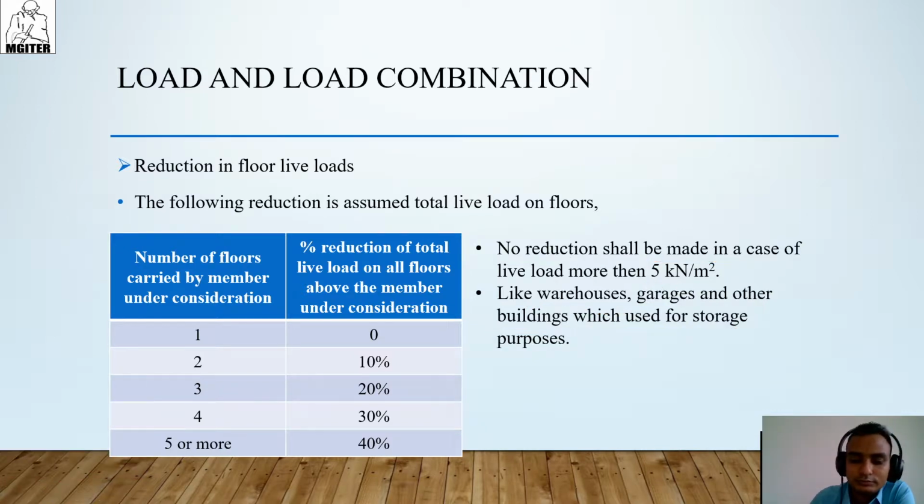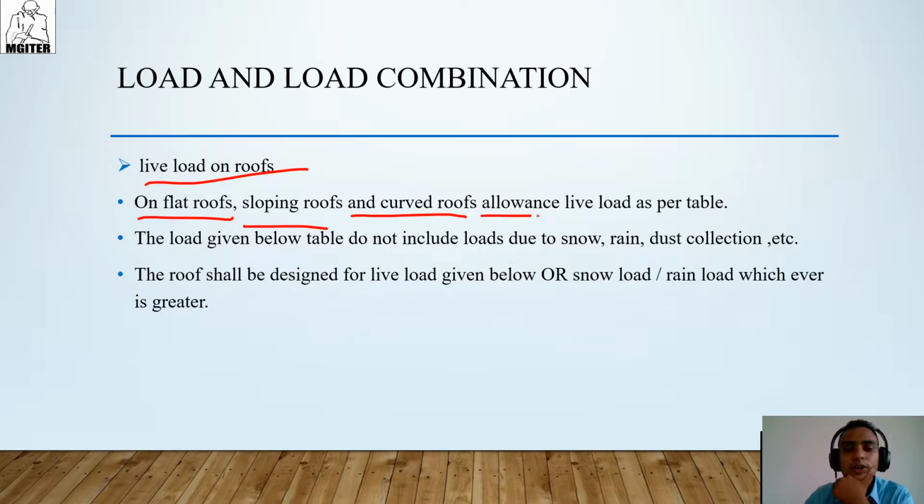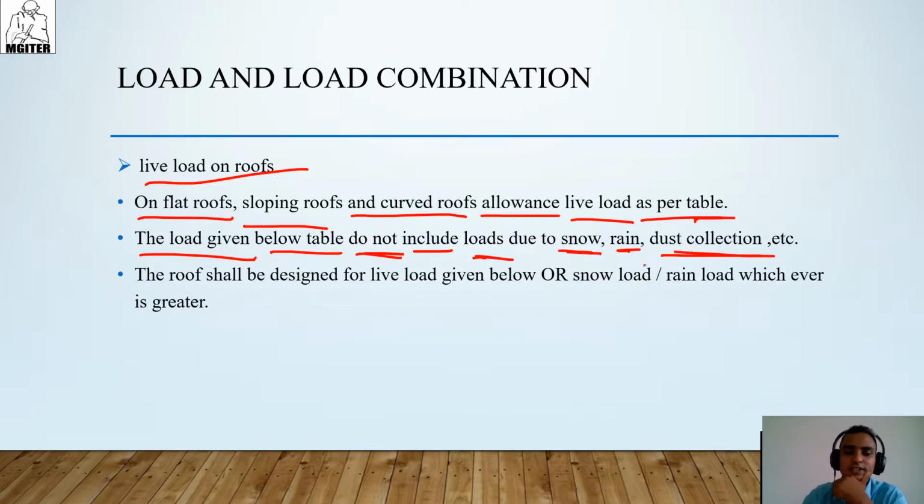Understood? Then after, live load on a roof, on a flat roof, sloping roof and curved roof, the live load is as per table. The live load given below does not include loads due to snow, rain and dust collection.